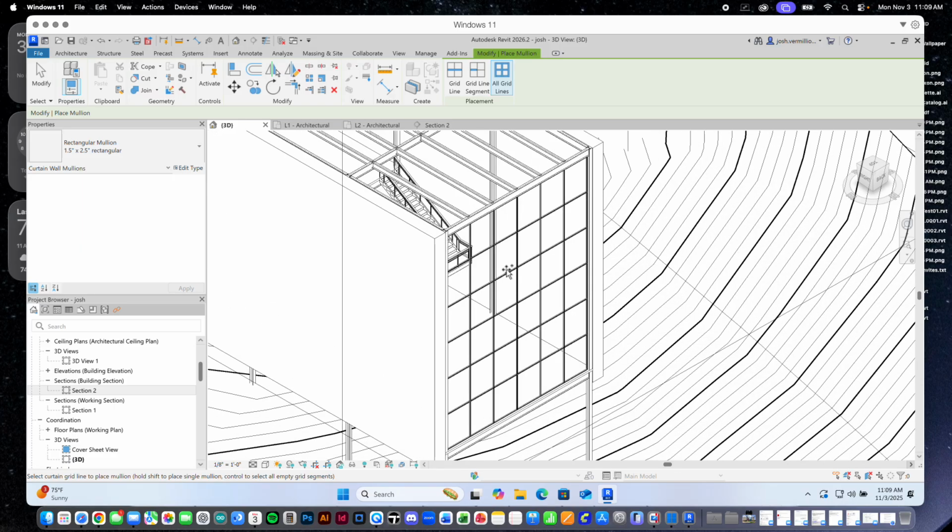Again, not the easiest thing if you've never done this before, right? Like the workflow is everything, trying to understand how to get control of this thing. Otherwise, it moves around on you way too much, right? So what I did, we made a curtain wall, we drew it in plan, we sucked it in, made sure that it's the right size. We counteracted the offset for the top to work within our structure, right? Not to collide and clash with our structure.